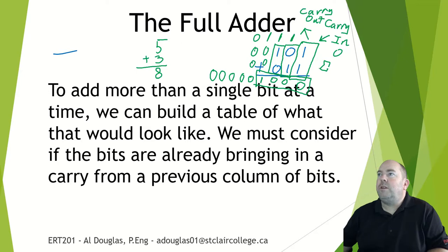Okay, so you can see this is creating a full adder, and one of these can be made for each individual column, and you can just string together these adders for as many as you need, one for each column. You're just considering a carry in and a carry out for each. Okay, and then we can add up huge binary numbers together just by repeating that operation.